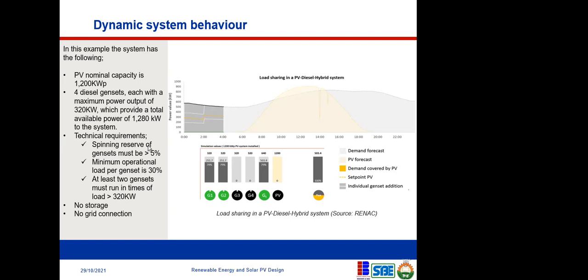So in case any additional load quickly comes up, your generator doesn't have to shut down. It should accommodate it. But this additional load has to be a transient load. Otherwise, you need additional generator capacity to keep them running. So spinning reserve is just trying to create that allowance. If any sudden load comes up, the generator should be able to accommodate it without shutting down the entire facility or knocking down the generator. That's what spinning reserve does.